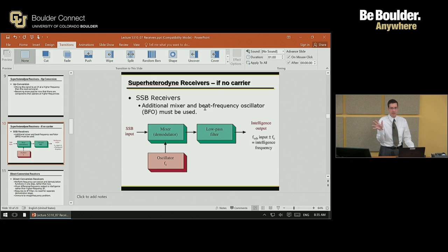If it's tuned to the right frequency, then you're able to demodulate the signal and hear it. What I was thinking about doing was going to my ham radio, which has a single sideband receiver built into it, and it has a frequency beat oscillator. When you tune to the station, it goes up and down, and then you have to get it right to where the person sounds normal.